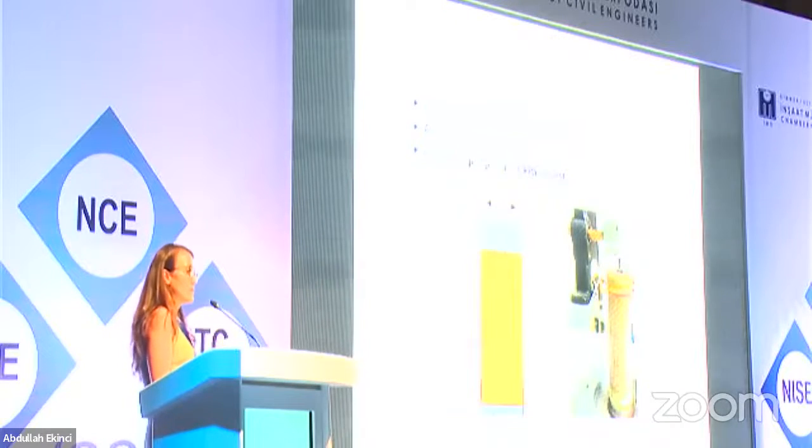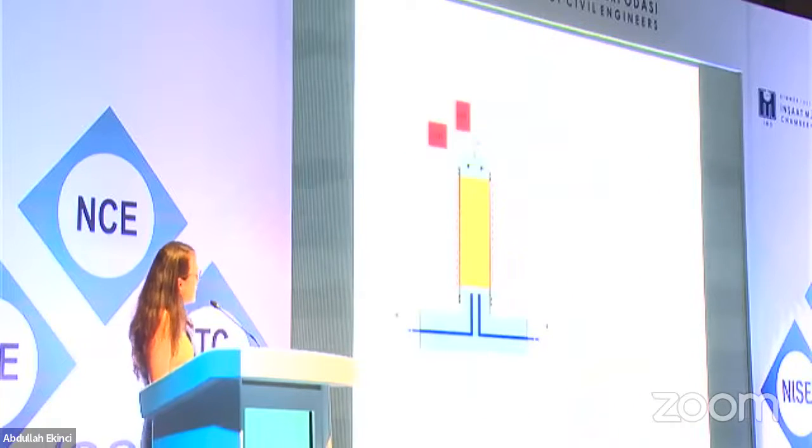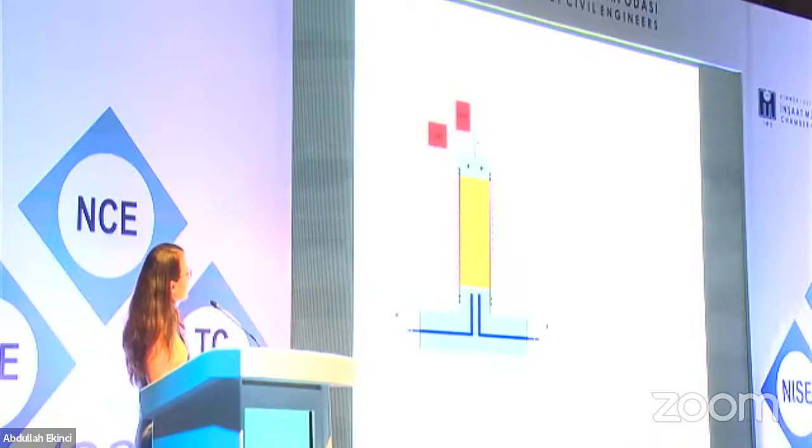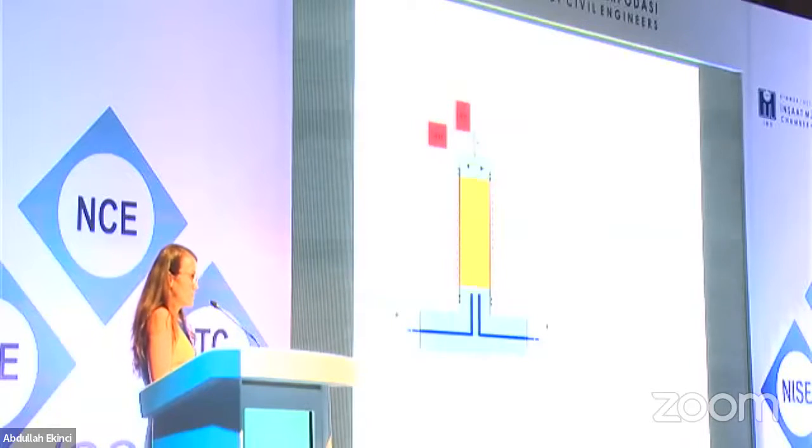Due to this loading, the specimen is swinging in horizontal direction, and this loading causes the evolution of pore water pressure. The evaluation of the test is very simple, and it follows from the very simple equation of effective stress. Now, the performance of a single test, I will explain using the schematic representation on the left-hand side, and I will support my explanation using the small diagram on the right-hand side. The x-axis of the diagram is denoting the loading cycles, while the y-axis is showing the evolution of pore water pressure. As you will later see, it's also at the same time the evolution of effective stresses.